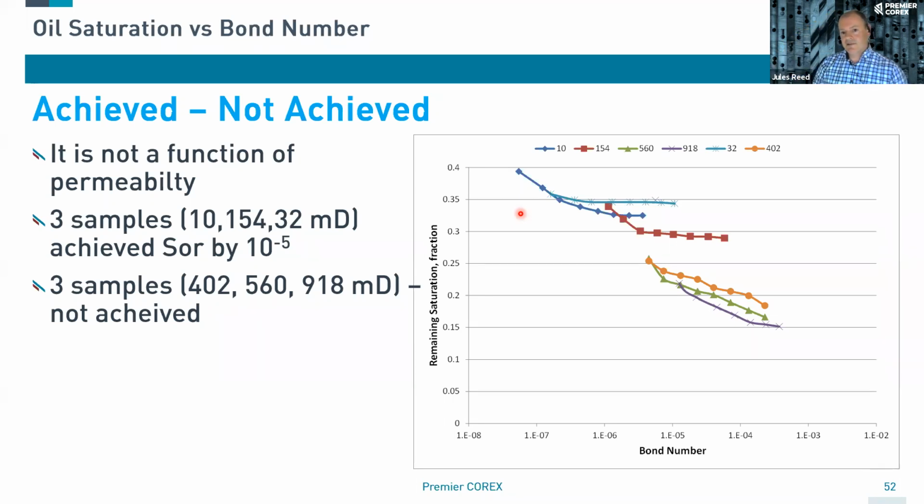So you have to think about a flooding system. A strongly water wet case like a gas system is one of the times when the capillary end effects have less impact on the residual saturation, so you could use core flooding for this.